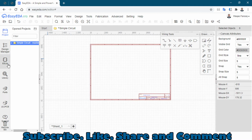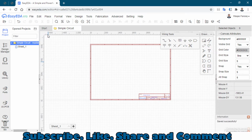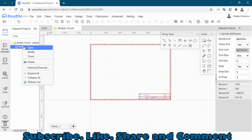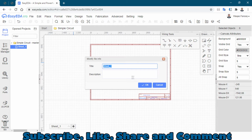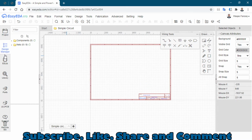First of all, you have to go to this left side, and here we have the simple circuit. Sheet is added. Now we have to go to file and click on save, or you can simply press Ctrl S. Here you can see we have sheet 1 added. You can also rename it by clicking on modify, simple circuit sheet, and you can type a description here. I'm just leaving it blank. Click OK.